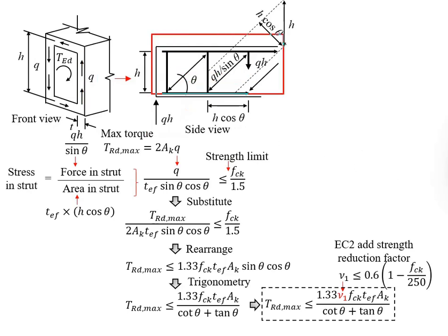And then we're going to look into the imaginary truss model. You have the reinforcement, you have the link, and you have the compressive strut. It behaves like a truss model. The reinforcement will contribute the tensile resistance, and the diagonal strut will contribute the compression.